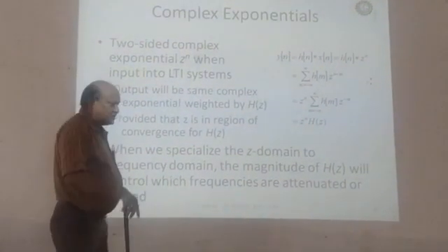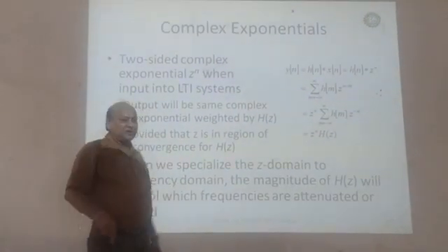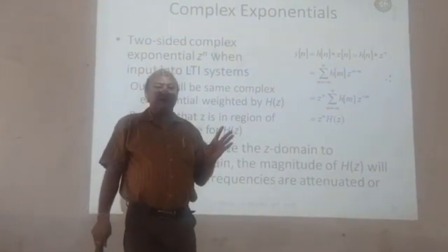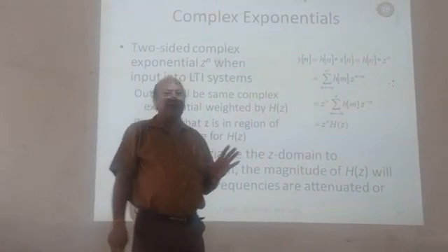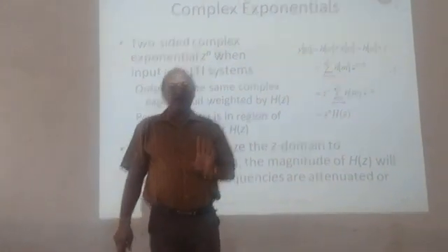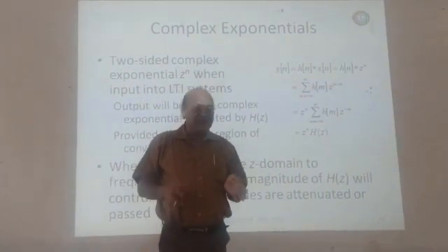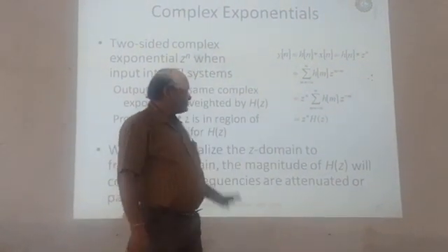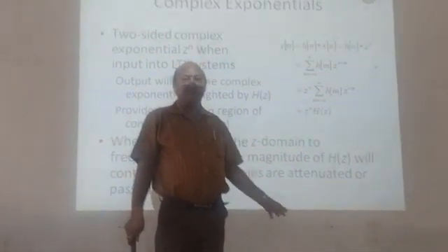And finally, for today's video, I will also tell about the complex exponential. The complex exponential plays an important role in linear systems. While analyzing a linear system, we can consider a complex input like e to the power j omega n, for the n number of samples. If we consider this complex input, then we will get the frequency response, magnitude response, as well as the phase response. So this is today's lecture about linear time invariant systems.